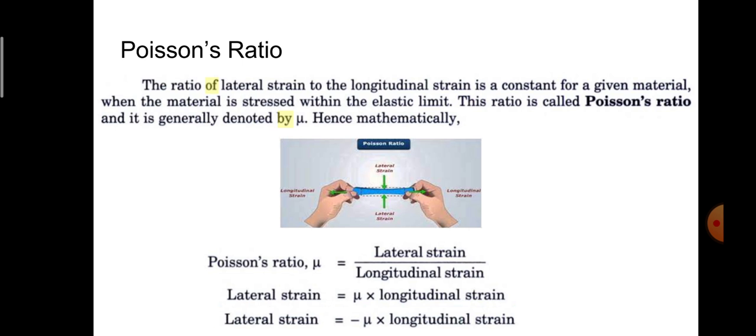I just repeated, when a material is stretched, as shown in the diagram, there is the linear strain observed along the direction of the load applied, and there is a compression in the perpendicular direction to the force applied.